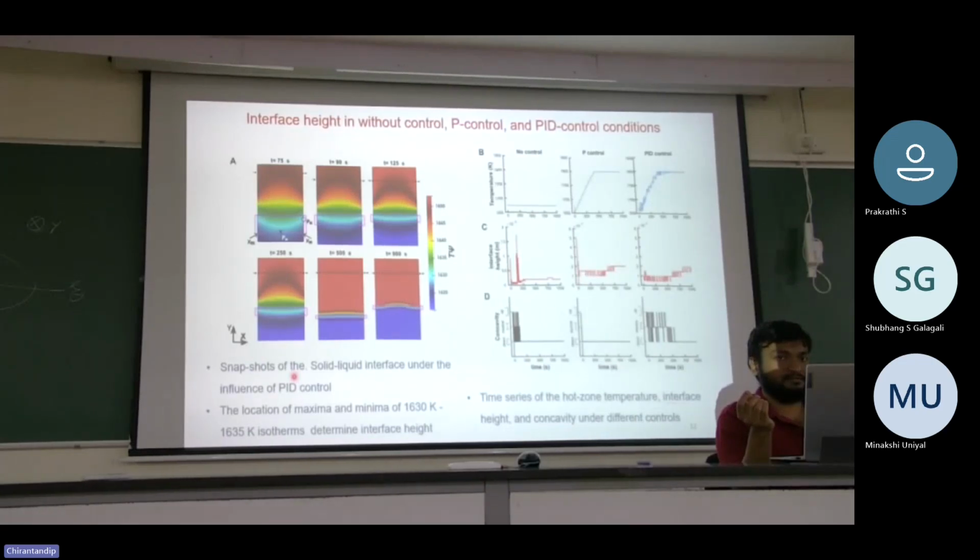So your solidification isotherm contour will be shaped like this, concave down. As you start going into the cold zone, you become more and more cold dominated, so the shape of the interface will become concave upwards. This is natural, you cannot avoid it. But it has consequences on how you grow the grains.